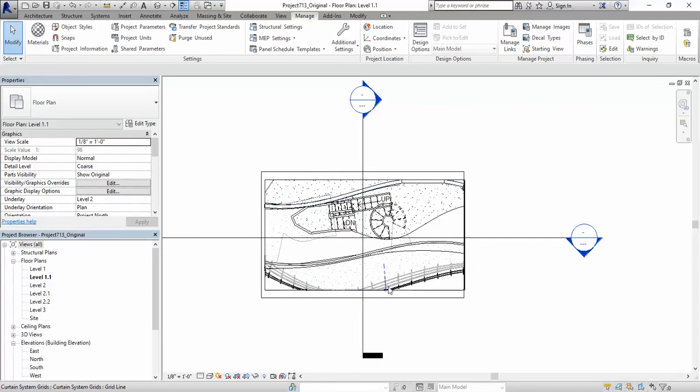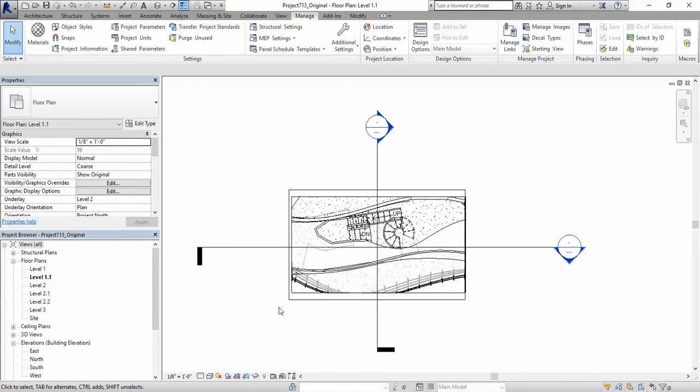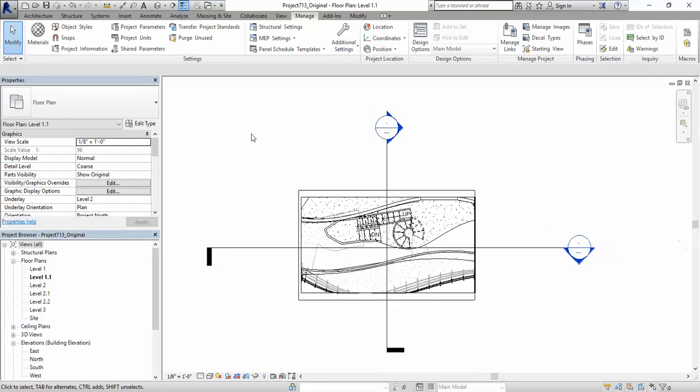As a second step, what I recommend that you always do is that you start orienting the actual building, in our case the gallery space, towards the true north. There are two different ways that Revit works. The very first one is the project north, which is basically the north that the actual project template has set up for us. And this, as you can imagine, follows the X and Y, so you guys can design and draw lines, walls, architectural elements easily in the perpendicular axis.